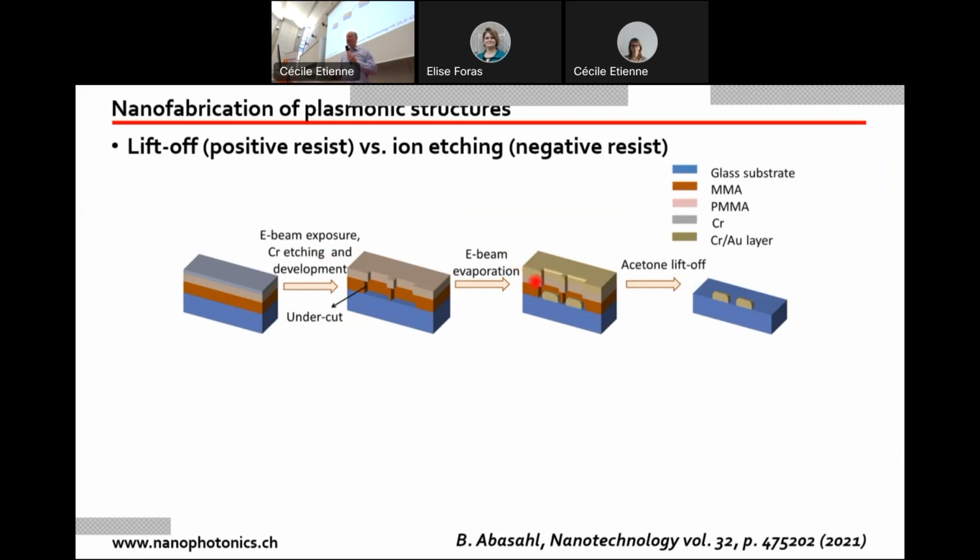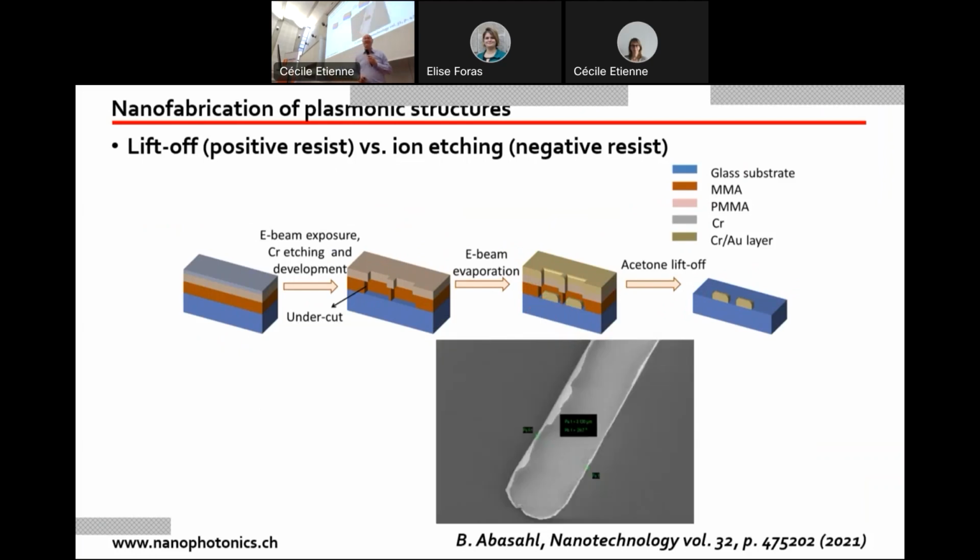And so there is an undercut such that the metal film is not continuous and it only cuts inside the cavities in the photoresist. If you don't do that, then you will tear your metal apart. So when you do the lift-off, there will be a continuous film here, and then it's just going to break somewhere, which is not really controlled. So that's why it's important to always use 2 photoresists if you do a lift-off approach.